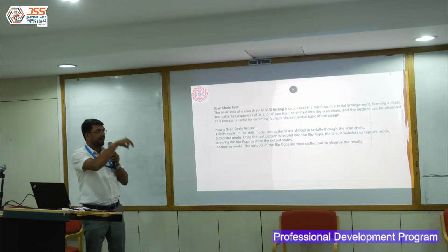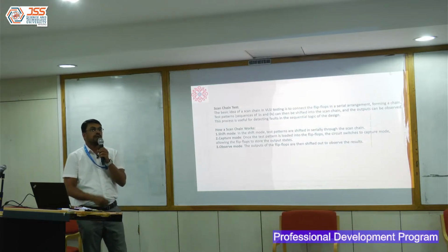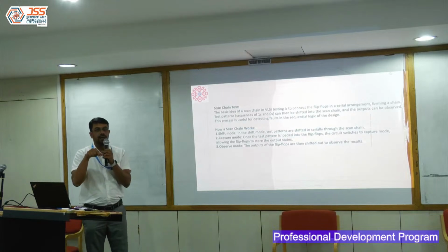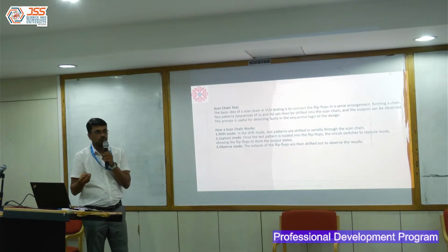Basically what we do is we add a mux in front of the D. The mux has a select line, and that select line I call the test mode.